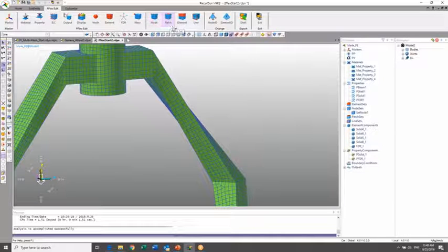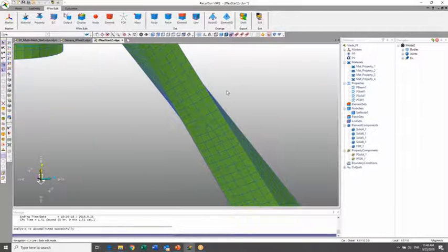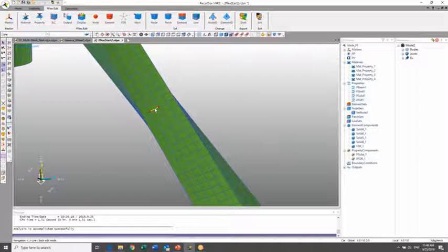If you click on one of the options of the set, it is to make a node set. And there are these new features to select between patch and line. So I'm going to go ahead and select the line there. I'll leave everything else the same and click on the add remove continuous. If you zoom in on that a little bit, it'll actually select two nodes as you're trying to select something. So if you're just scrolling over your elements, it'll select two nodes at a time.